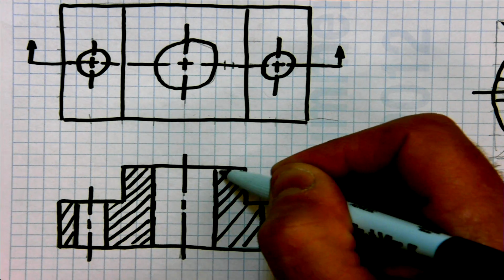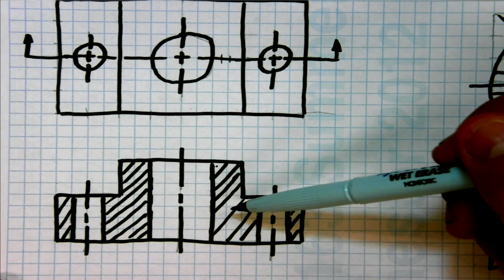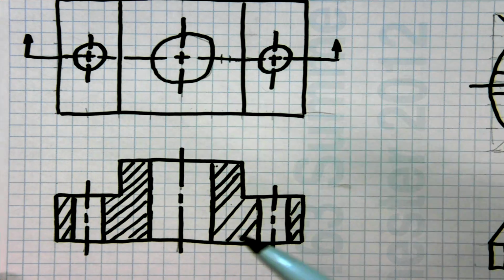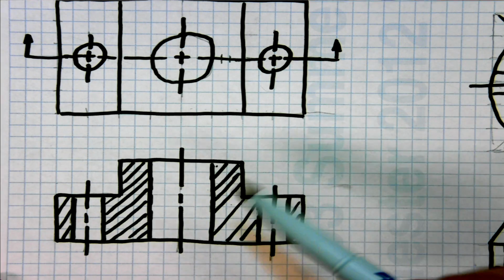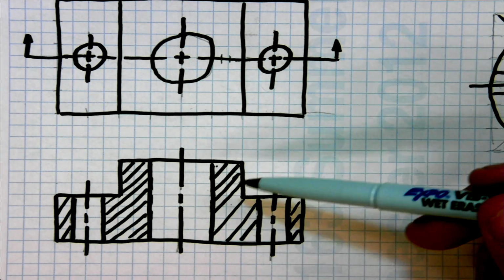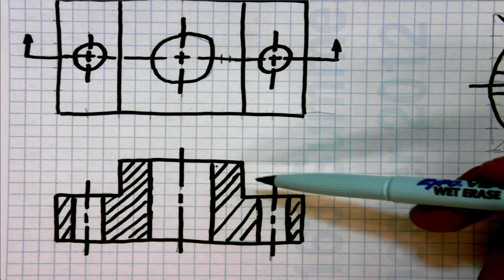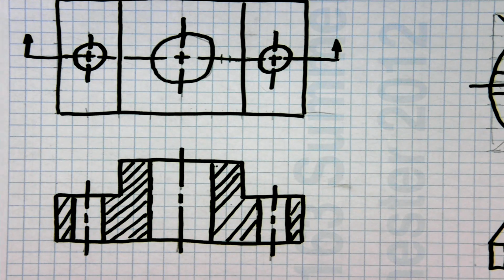Let me show you some good examples and some bad areas. These are pretty consistent. These get a little bit spaced out. So you want to try to stay consistent with these things. You don't want to confuse somebody into thinking there are two different types of cross-hatching, because if you had cross-hatching here that was different than this one, then you're assuming this is a different part, which is not. This is actually one single part.